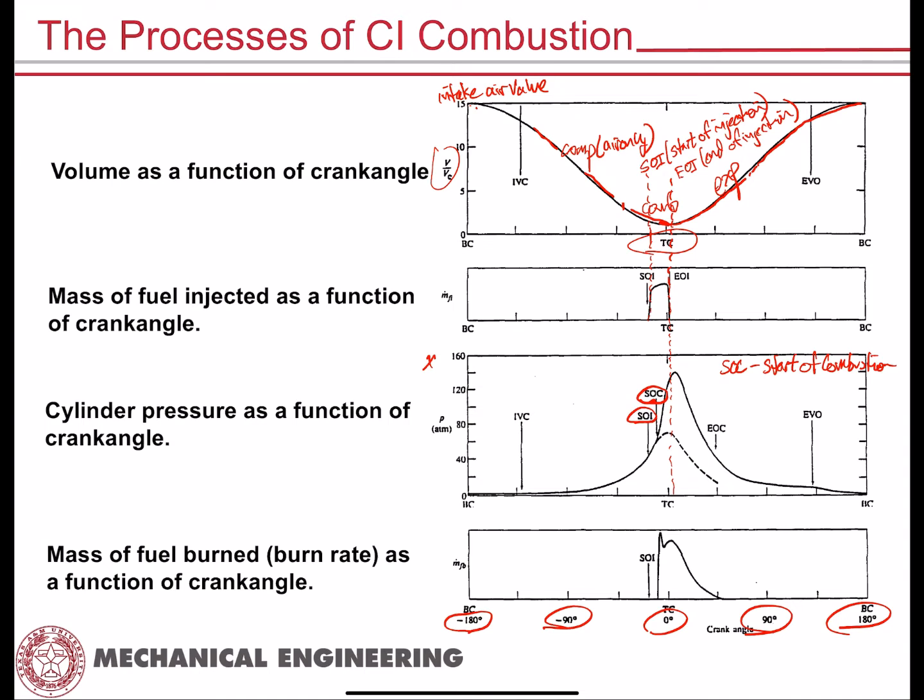But this ignition delay period, that's the time between start of injection and start of combustion, right? So that delta there is what we call the ignition delay. So you have this ignition delay period, and then combustion eventually begins. And of course, as combustion proceeds, now your cylinder pressure starts to rise, right?